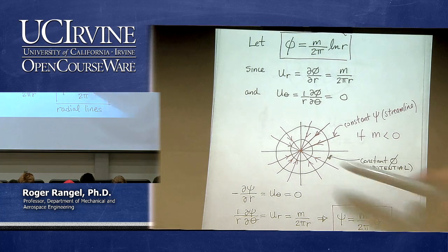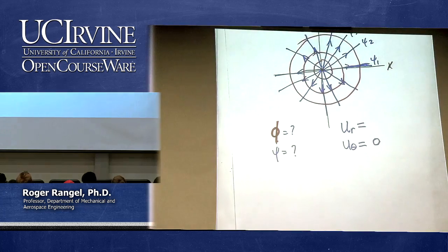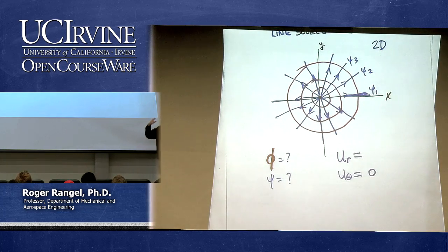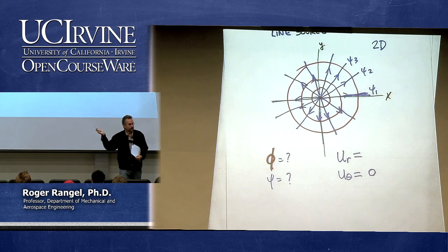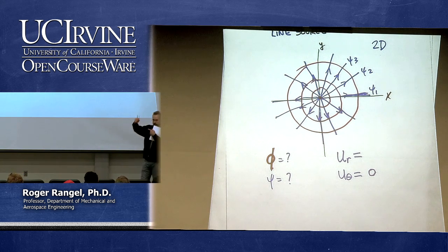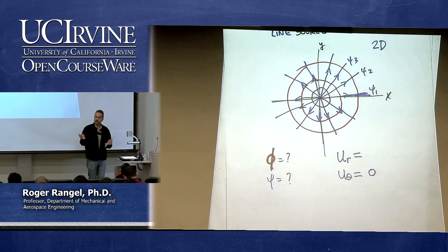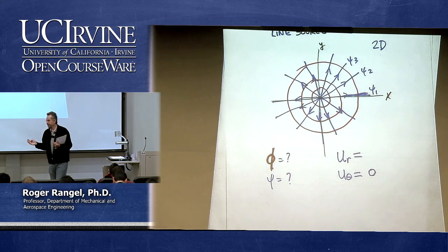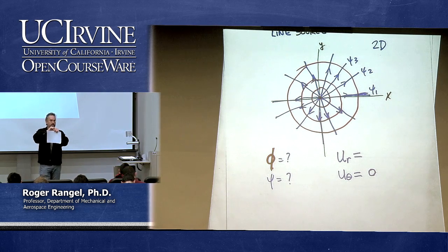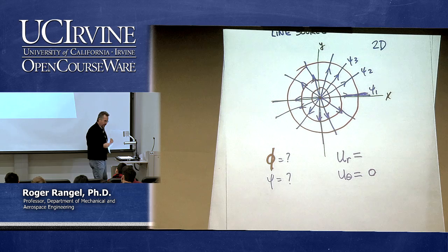As I go out, the flow, this one is a sink so I have it drawn in, but if we look at the previous one, it goes through a larger area as it goes out. So then what? Mass conservation. The velocity has to be lower so that it matches the increase in area, and the actual flow rate is constant. Otherwise, somehow you would be making new mass. So the mass all came from the line source, is spreading radially outwards. It has to decrease in velocity so that mass is conserved.